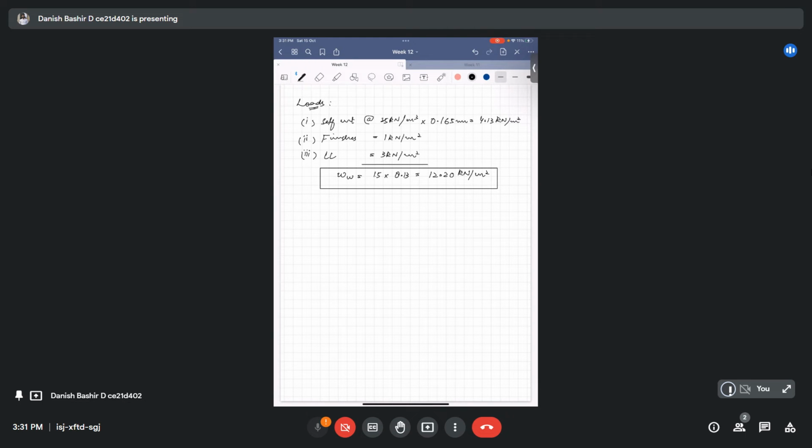So we will calculate the design moments from which we can get the reinforcement. Okay, so I already told you the corners are torsionally unrestrained, that is they are allowed to lift up, so we can use the methodology that I already explained to you. Design moments we will calculate from the moment coefficients. Short span Mux is alpha x times Wu Lx square.